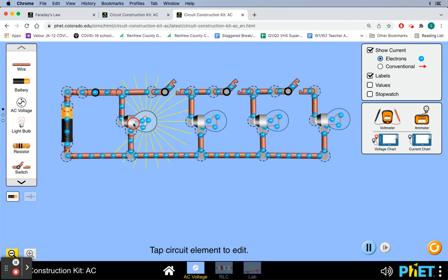If you then plug in another device into the outlet, let's say I've hooked up an extension cord or power bar or something, and I can plug many things into this outlet, what you're doing effectively is wiring more and more devices in parallel with the outlet.